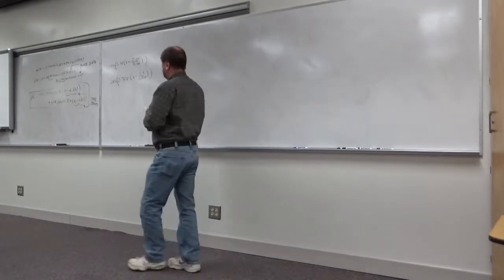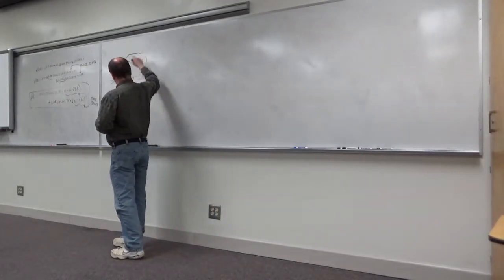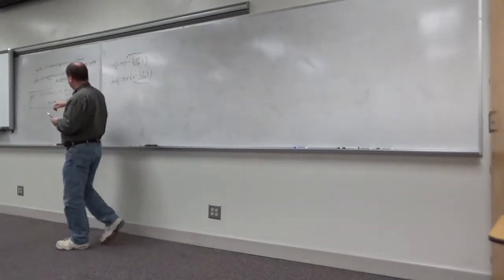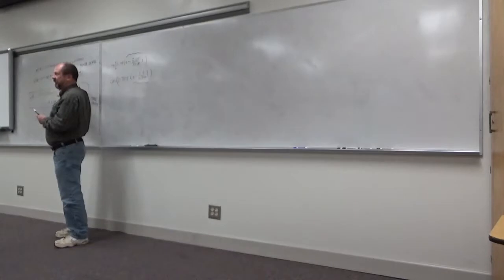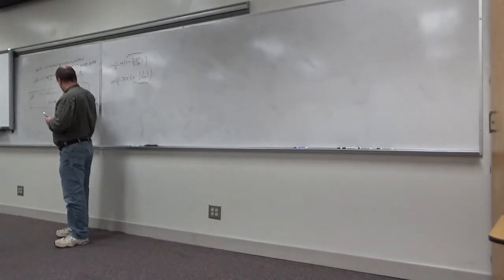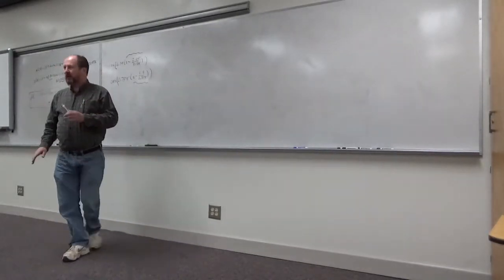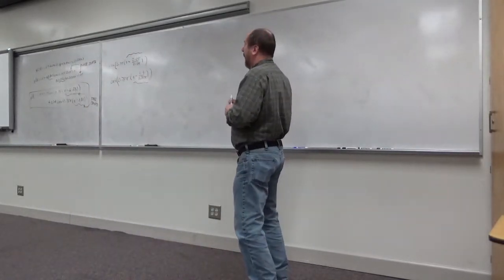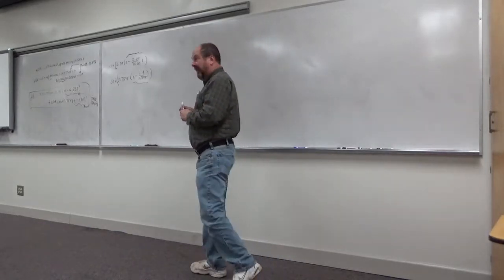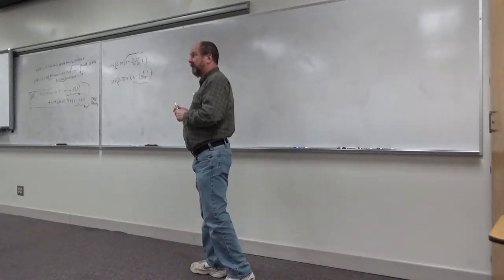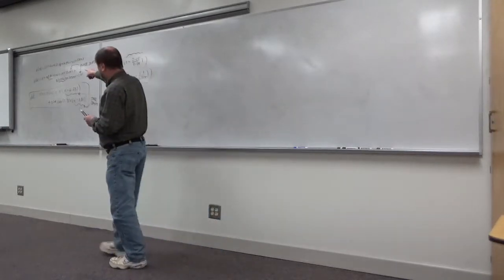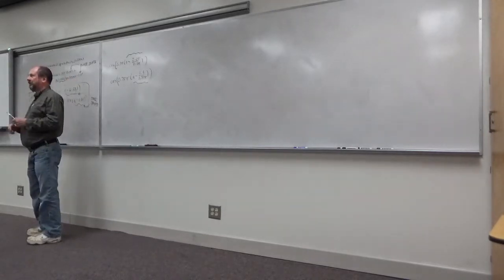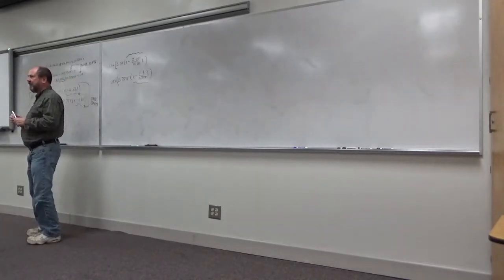Okay, so does this look like a time shift there? Now, I don't want you to be worried about n minus 6.53, the fact that it is not an integer, or n minus 0.81. That turns out to not be a big deal. If you want to know more about it, talk to me outside class and I'll explain it. But is n minus something a time shift? Okay, yeah, so what this tells you is a phase term is just a time shift. That's all it is.